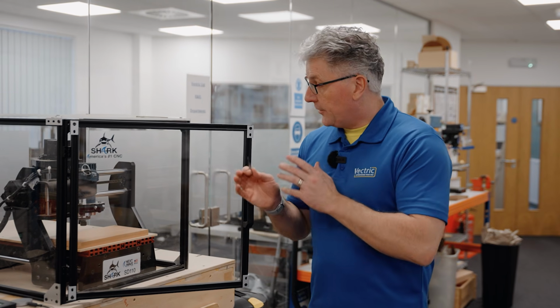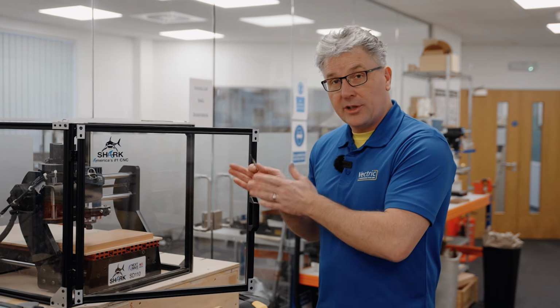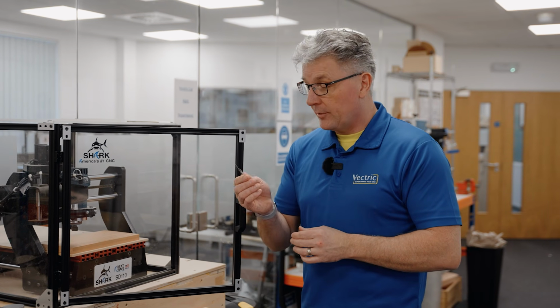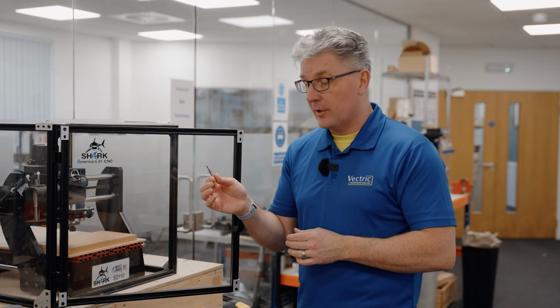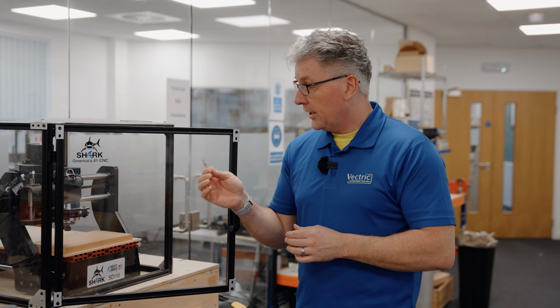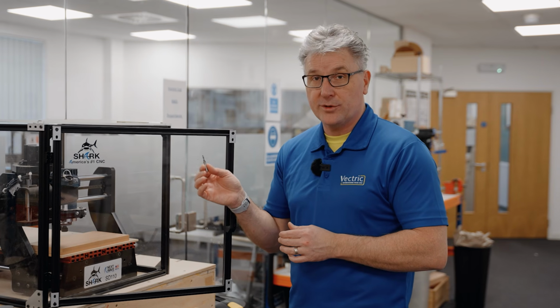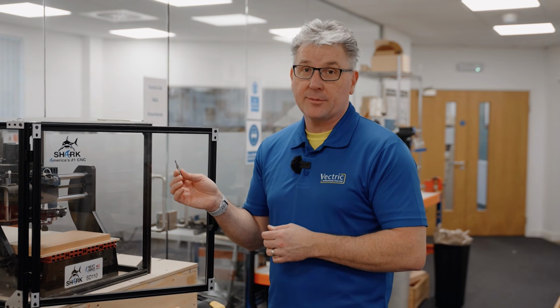Okay, so there we have it. I've got my material securely positioned on my wasteboard of the Next Wave CNC. Now what I'm going to do is I'm going to go ahead and insert in my 1/8 inch end mill tool into the collet, and then we can go ahead and set the machine up like we have told the software it should expect it to be set up.